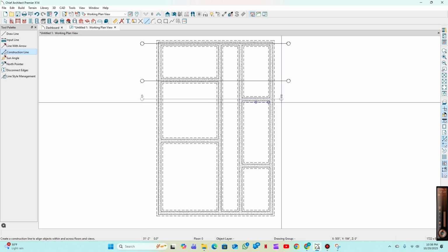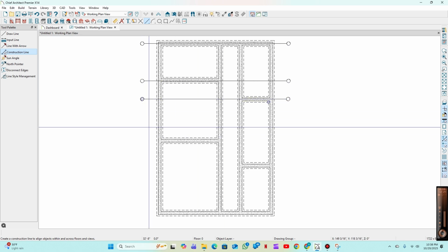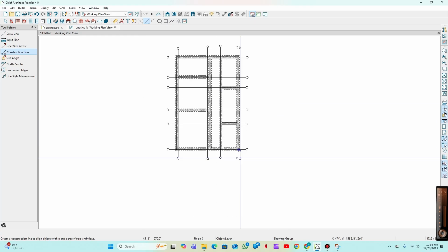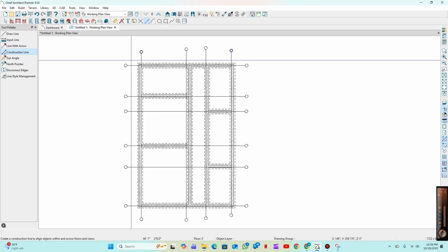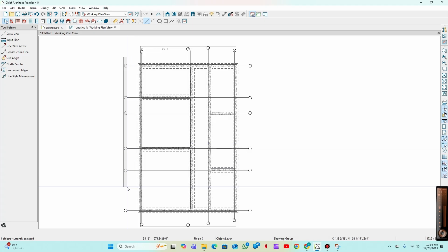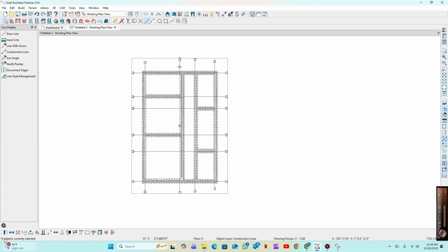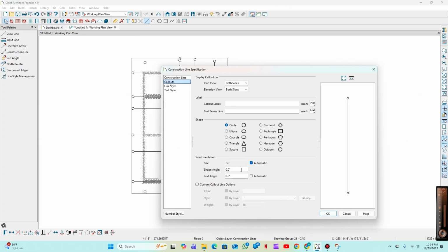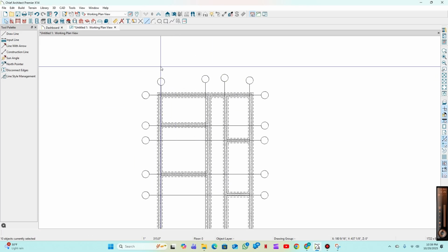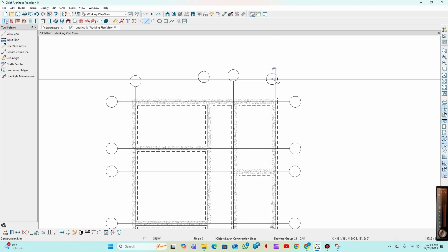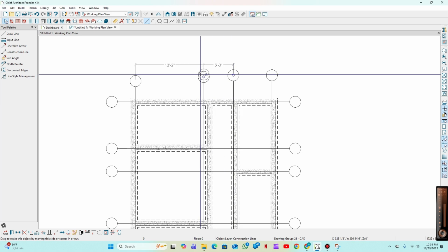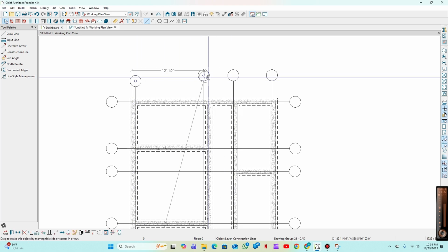So before it, I finished the entire thing, and then what I did was I selected all of the grid lines because the boxes are too tiny for me. So select all the boxes and open the properties up, and then you untick the automatic option, and then instantly you get the bigger ones. Simple. Just from here, you align them how you want to place them. I prefer everything to be straight, and also everything has to be aligned. So you have to decide how you want it.